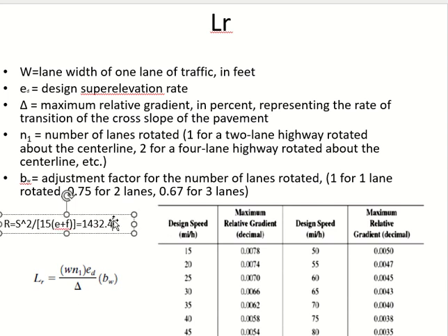How did they get it in the question? Because there is a table for it. And from where did we get the table? I have already explained it, right? Very good. So f is 0.12 for the speed of 60 miles per hour. F is 0.12. How much is the super elevation now? Tell me.